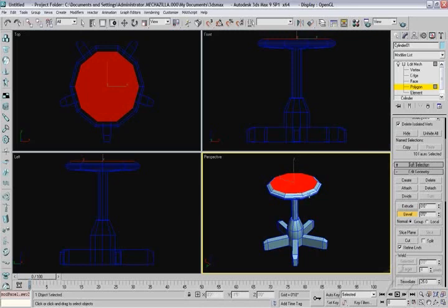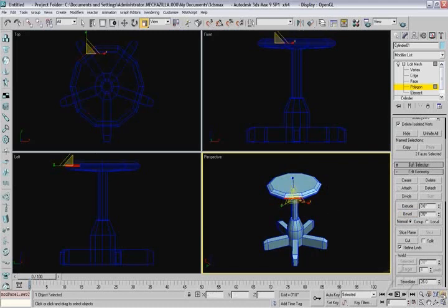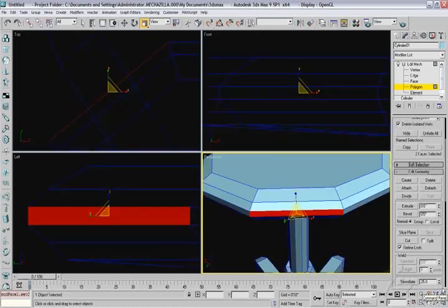that come off the back that hold the back onto your office chair. Now you can do this depending on your chair. If you want to pull them off the back of the seat, or if you want to pull them off the pipe, it's entirely up to you. I'm going to use the chair seat itself, so I'm going to get out of bevel mode by clicking back on it and clicking on one of these side polygons right here, and using my Zoom Extent selected, which if I hold down my left mouse button over my Zoom Extents All, gives me the white 3D cube with the 4 red squares, and it will zoom around my selected face.